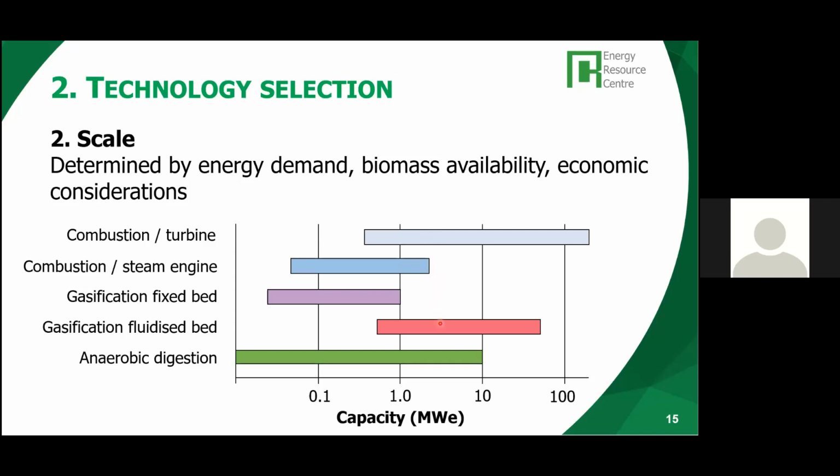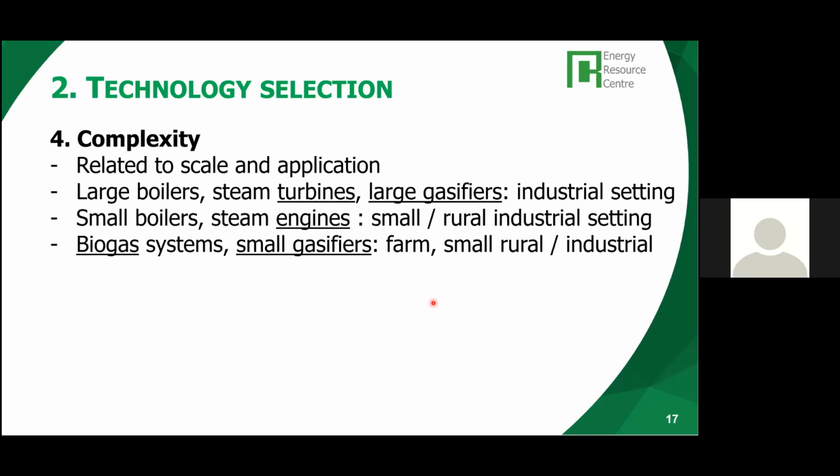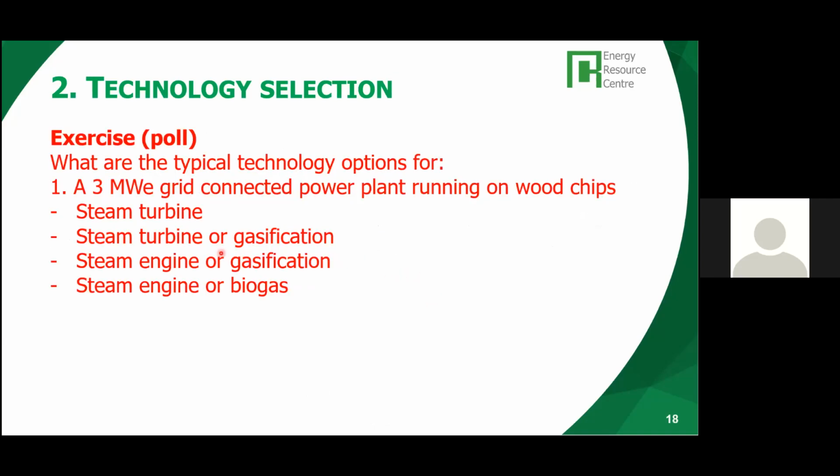Secondly, gasification would also be a possibility. Let's say fluidized bed gasification would be appropriate at this scale, although it's also possible to use several fixed bed gasifiers running simultaneously in parallel to add up to 3 megawatts. So basically, the right answer would be steam turbine or gasification.